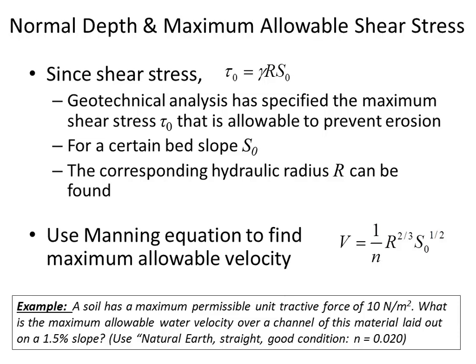So that if we solve that in the Manning's equation, 0.068 meters to the 2/3 power, and the slope 0.15 to the 1/2 power, then the maximum velocity in this case that should be allowed to go through the stream is 1.02 meters per second.